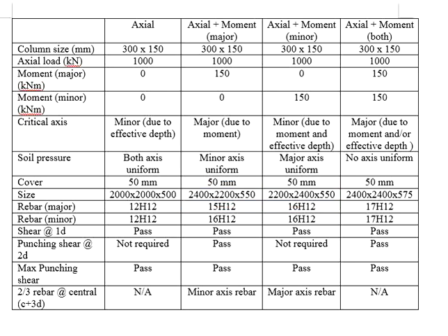the moment is greater. Now in this case, when you have moment in both axes, it is harder for you to define the critical axis. Normally, the critical axis will go for a greater moment. If the moment in the major axis is greater than the minor axis, then it is likely the major axis will be more critical. Otherwise, the minor axis will be more critical. In this case, when you have the same moment in both sides, we will follow the rules of the square sections, where the minor axis will be more critical.